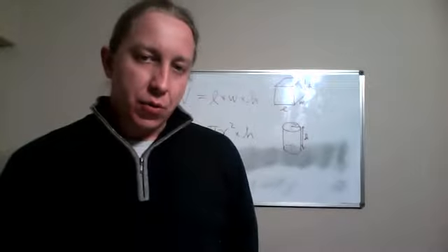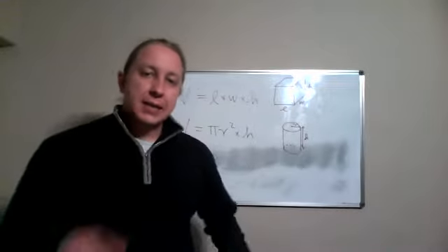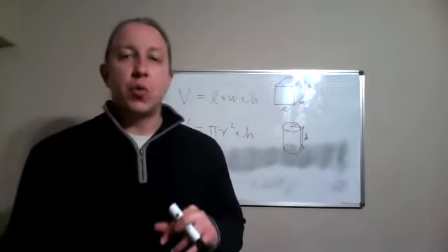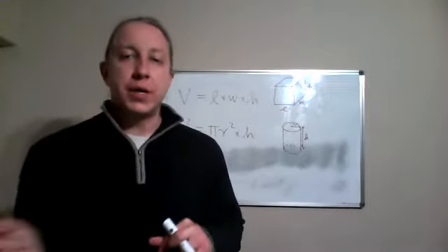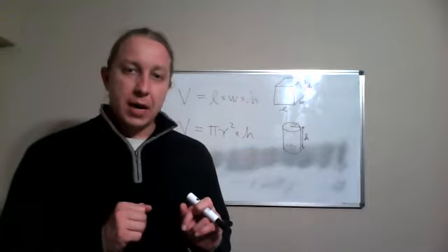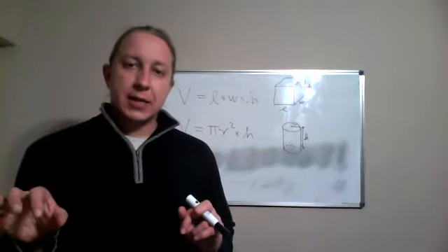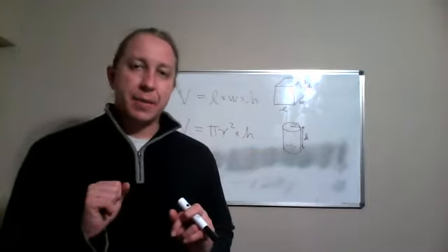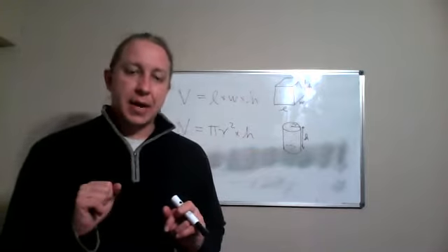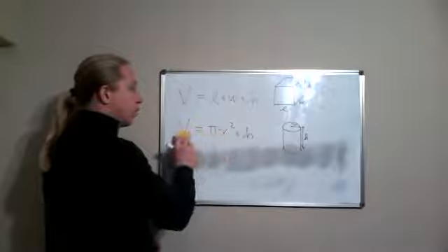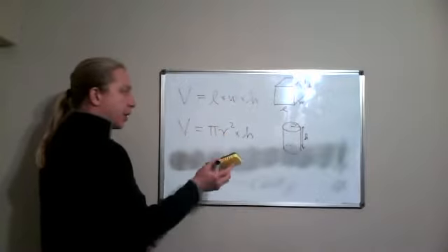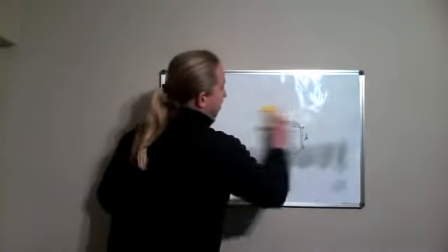Do you see how they're asking the question backwards here? They're not saying, here's the dimensions of our tank, how much water is fitting into our tank. They're saying, here's two of the dimensions out of the 3 that we need. There's 500 kiloliters in the tank. What is that other missing dimension? All we have to do is write out the correct formula and solve for the unknown that we have. So let's do that.